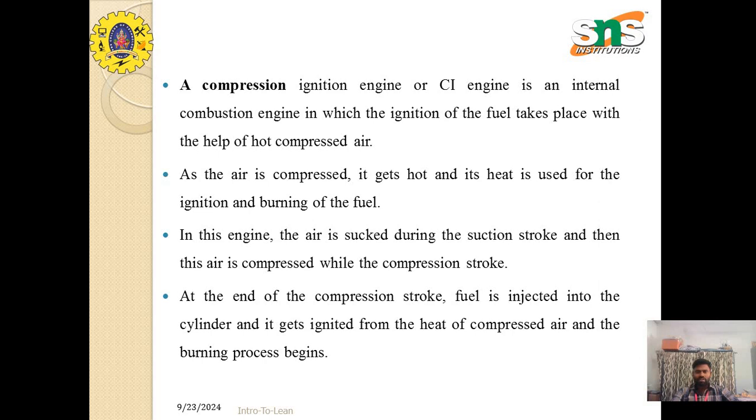In this type of engine, air is sucked in during the suction stroke and compressed during the compression stroke. This is the 4-stroke cycle of the CI engine, where air is sucked into the combustion chamber and compressed, then fuel is injected into the combustion chamber, and then the exhaust stroke takes place. At the end of the compression stroke, the fuel is injected into the cylinder and ignited by the heat of the compressed air, and the burning process is initiated.